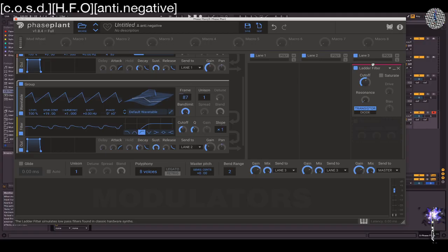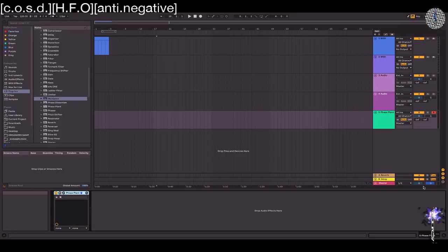So summing literally is always happening at all points whenever you're listening to music anywhere. Summing is always having an effect. So summing engines, we talked about this, I believe, day 1 of like sampling class on bit depth and what sample rate means. But your summing engine literally is your final cup. So it's 32-bit float, 64-bit float, whatever that is for your DAW, which means how it affects the signal whenever a signal's turned down. So if you had a bad summing engine, if you turn down your master, you lose bit depth. So 0, you get 24 bits, but if you pull down by 12 dB, you lose about 6 bits.